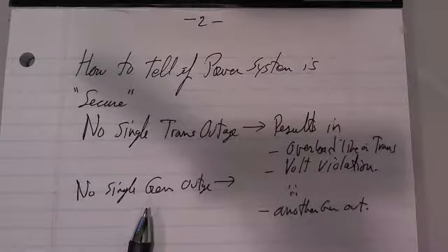And there are schemes where if you lose a generator, the frequency goes down, they can do what they call under frequency load shedding. That's a way of basically compensating. But you don't like to do that because you've got customers that, on a nice hot afternoon, you turn their power off. They can't run their air conditioners. The lights are out. Well, they can go out and cook on an outdoor grill or something. People don't like that.